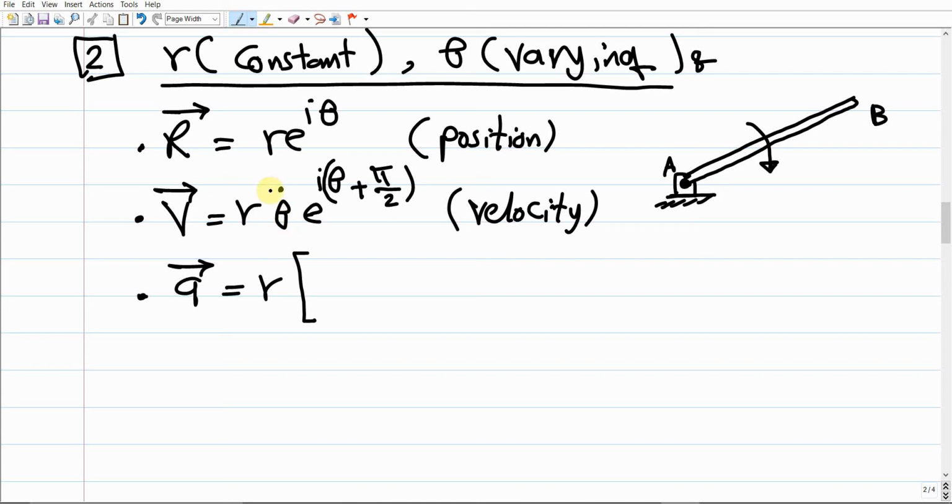So it means that there is a derivative of theta dot to be theta double dot, and there is a derivative also to the other term, which is the exponential term, because it includes theta, which is a function itself. It is a function of time. So this is the derivative of two multiplied functions of time dependence. So what we're going to do is fix the first term, then multiply it times the derivative of the second term. What is the derivative of the exponential term? Again, you're just going to multiply by the derivative of the exponent.